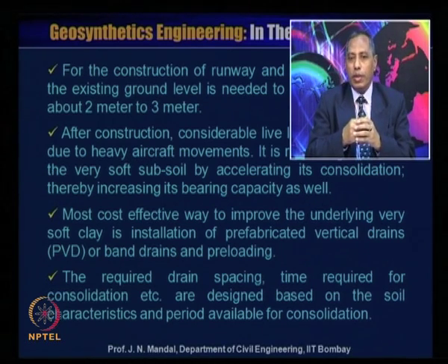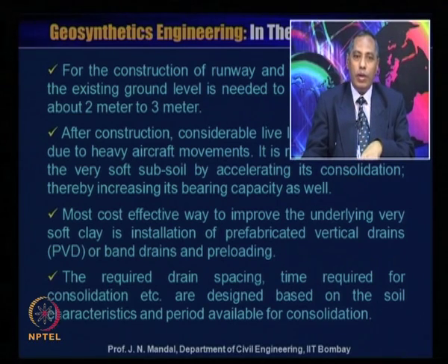The most cost effective way to improve the underlying very soft clay is installation of prefabricated vertical drain or band drain and preloading. The required drain spacing, time required for consolidation etc. are designed based on the soil characteristics and the period available for consolidation.